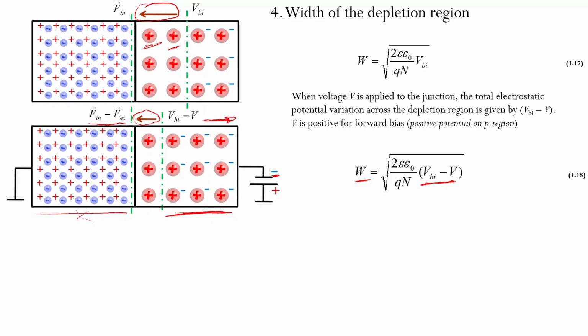Resistance of the depletion region is much higher, means that the total resistance of the p-n junction will be actually determined by this depletion region. And now you see, you go from case when you don't apply any potential, to when you apply forward bias, the thickness of this depletion region reduced, means the resistance of the p-n junction also was reduced.